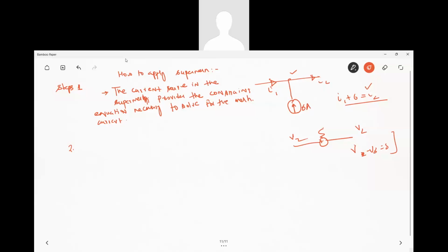Either you can take the supply, or you can take it like this, plus minus. If it goes from minus, you can take this as plus. Then you have to take the resistor value as minus. The equation remains the same. There are two sign conventions. I showed you only one, and you have to apply only one. In some books, you will see the opposite: instead of minus 15, they are writing plus 15, but for resistors, they are writing minus. That is also correct. That is one sign convention. Another is if you are taking this minus, that you take plus. You are getting my point.